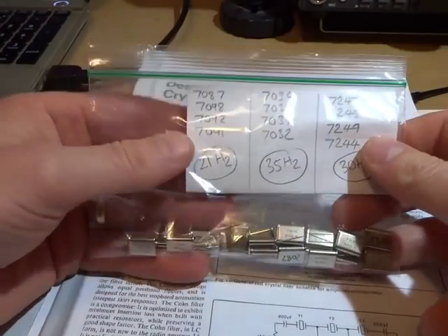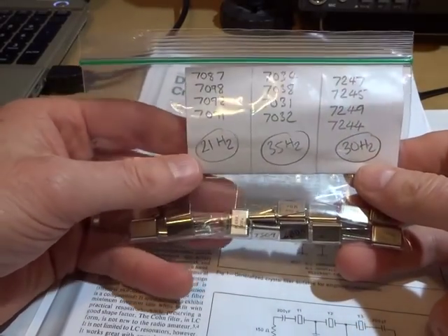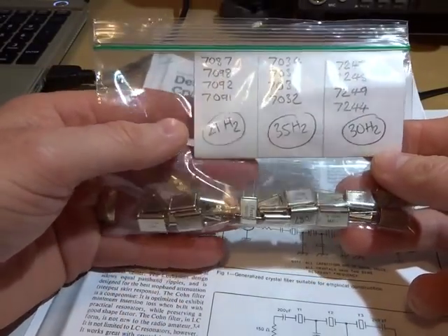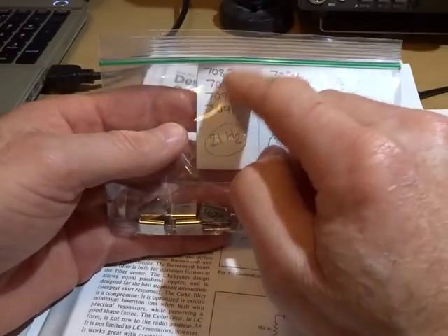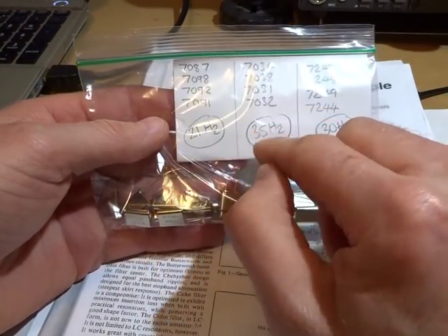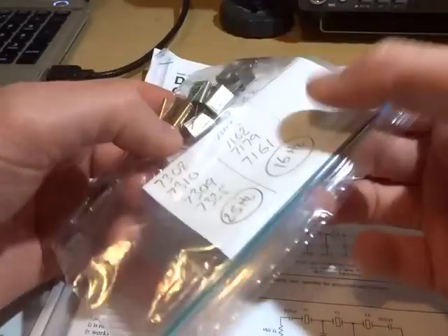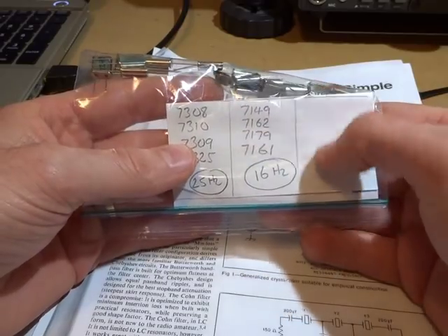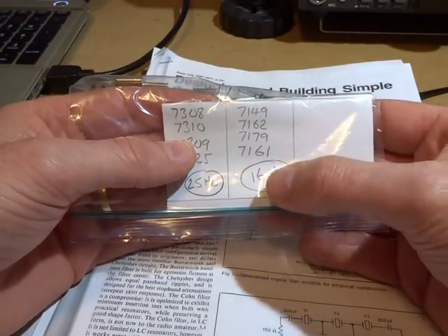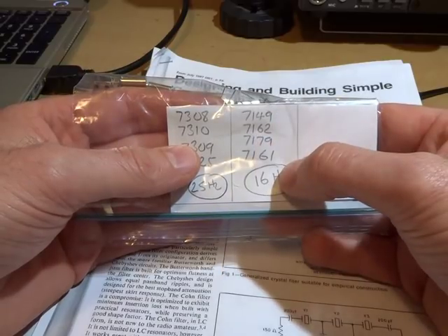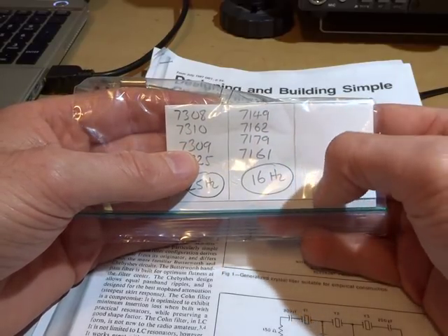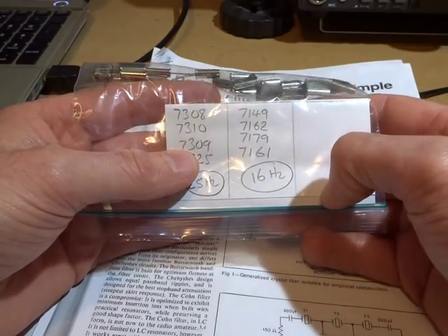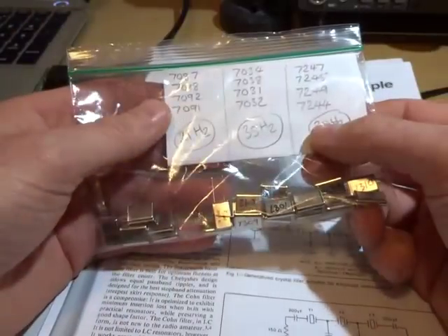So through the process just before, I managed to get enough crystals at this stage to do 7 filters. For example, the leftover ones here: there was a group of 4 here that were within 21 hertz, another group here within 35, 30, 25, and here's a group here which was 16. I chose 2 lots that are not here. One was within 15 hertz. I got 4 of those which I'm using for the SSB, and another one which was around 20 hertz across the lot, which will be the 6 crystals I'll use for the CW filter.